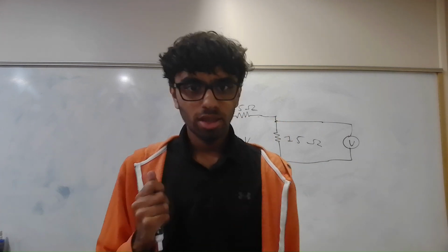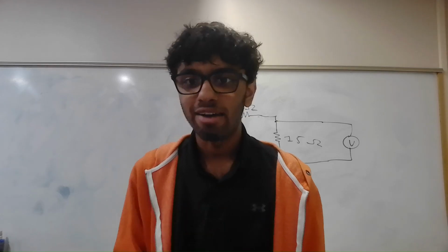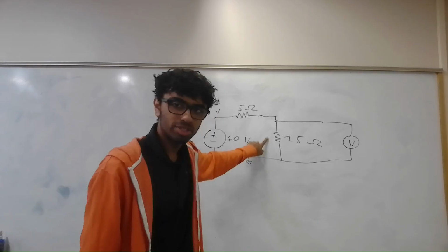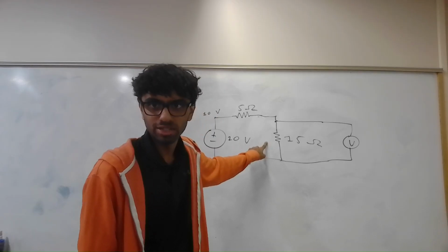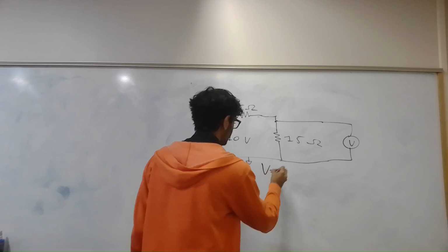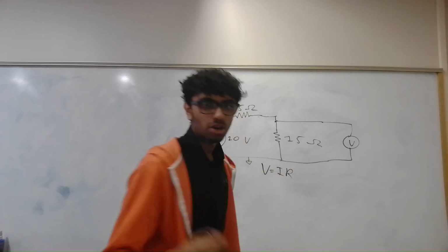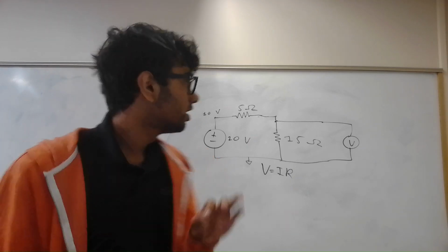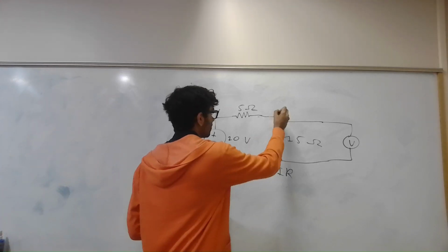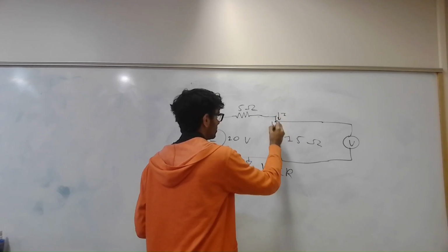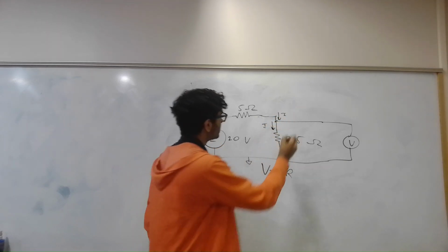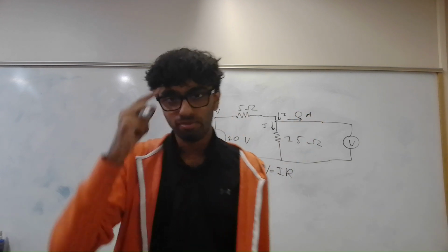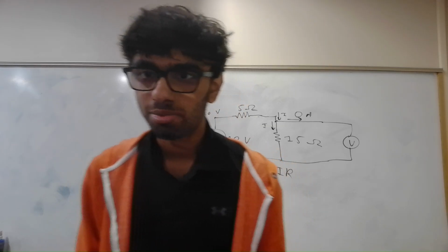Now, what property does this voltmeter need to have? Well, if I change the current flowing through this resistor, I change the amount of voltage that it's dropping, right? Because V equals IR, and R is fixed. So if I change I, I'm going to change V. But I don't want to change V. I need V to be fixed. So I can't change I, meaning that whatever current goes into here has to be the same current that goes into here. And 0 current, 0 amps, has to flow to that voltmeter. Otherwise, we're going to read the wrong voltage drop.